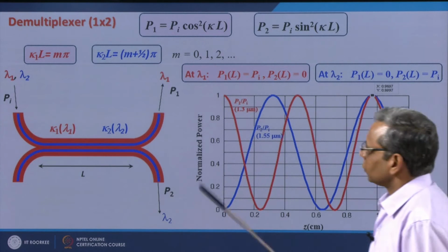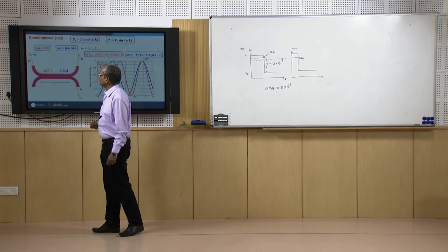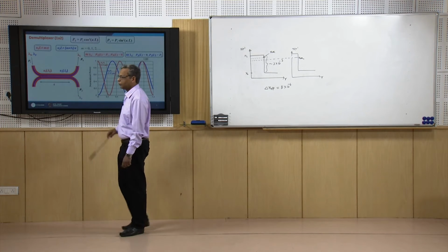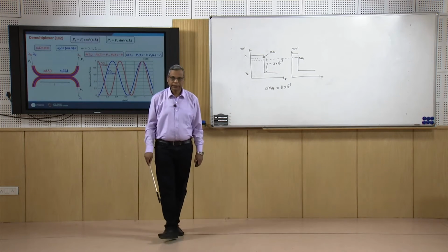So, what am I able to do with the help of this? I am able to separate out two wavelengths into two different fibers. So, this works as a wavelength demultiplexer.